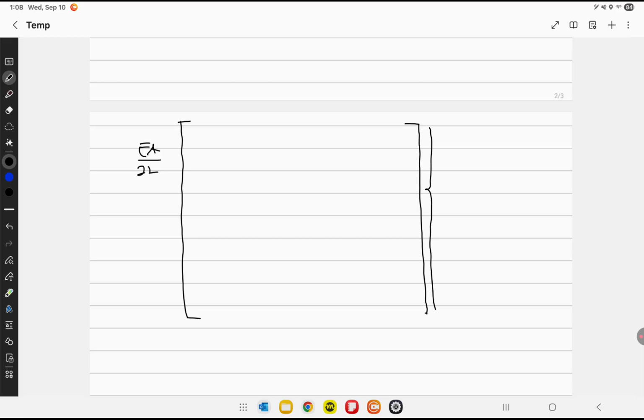And then there is a rule. You cannot change the order of nodes. However you define the connectivity of the element, your global vector will always have U1, V1, U2, V2, U3, V3. This is by the rule, because the computer has no idea how your elements are connected. It only knows the vectors from 1 to n in all degrees of freedom, and it's your job to assemble them in the right location.